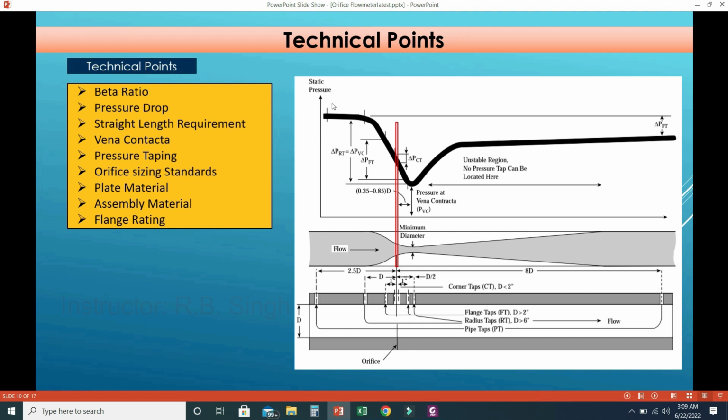You can see this is the upstream pressure. Just at the orifice it goes down. Again it will try to recover its value, but it cannot recover 100%. So this is called loss. This cannot be achieved. If this value is more than the allowable pressure loss provided by the process, that means the meter is not suitable, because it will not follow the process energy and mass balance equations. So we have to change our meter size, or recalculate with a different strategy.